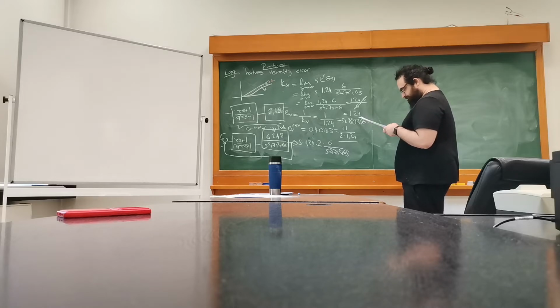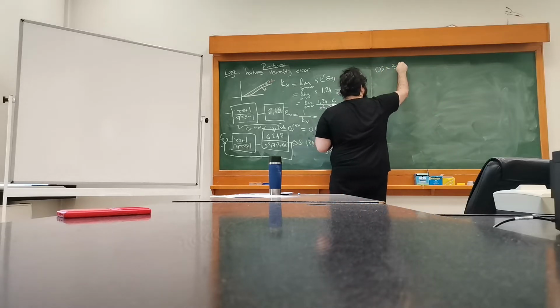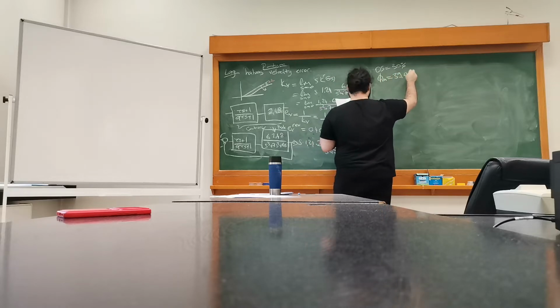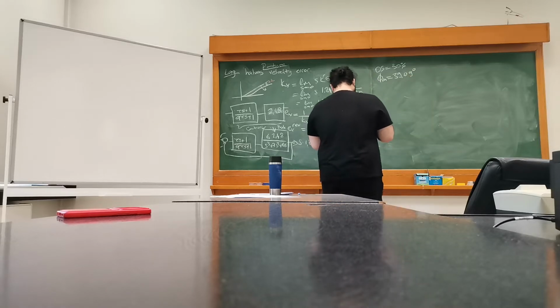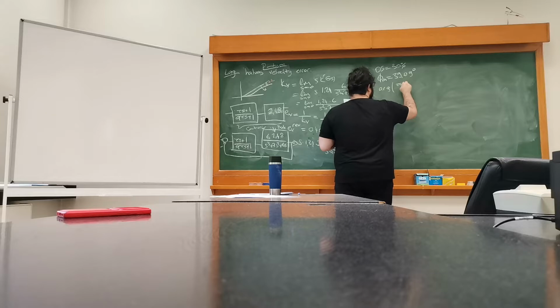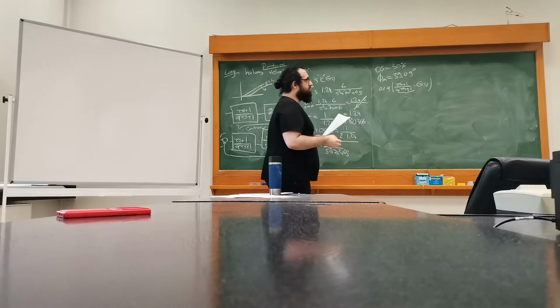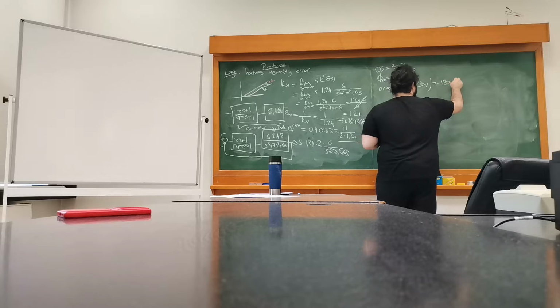Well, yeah, remember that we want to have overshoot 30%. Therefore, we had a phi m of 39.09 degrees. So these are still there, but if you remember, we have the argument of tau s plus 1 divided by alpha tau s plus 1 times G(s) basically. And this will have a certain effect on the phase angle, but we want to have basically minus 180 degrees plus phi m.